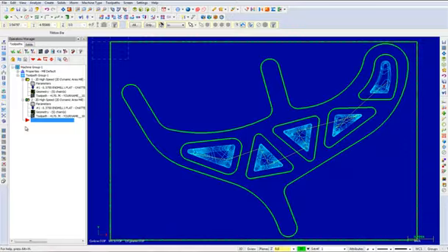From here, we will use a dynamic rest mill toolpath. In this step, you will delete one of the chains that was completely machined in the previous operation and does not require a rest mill operation. Then, you will change the toolpath type and the parameters to generate a 2D dynamic rest mill toolpath. The dynamic rest mill toolpath machines the areas inside of the pockets that were not machined previously due to the size of the tool. To delete one chain from the second toolpath, select Geometry in Operation Number 2.